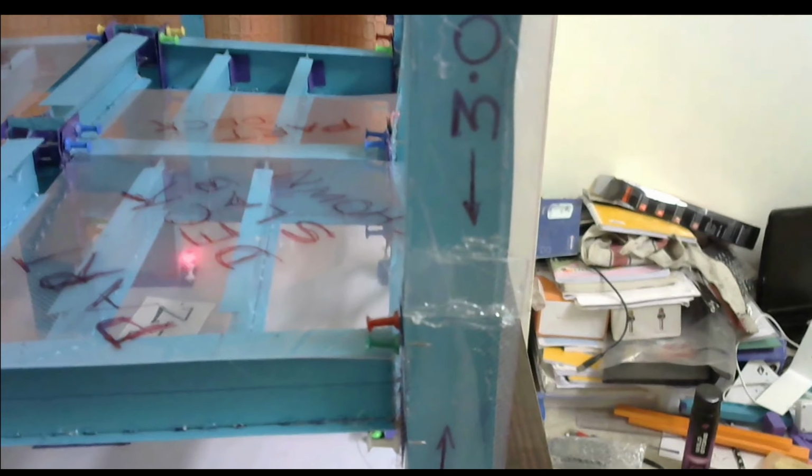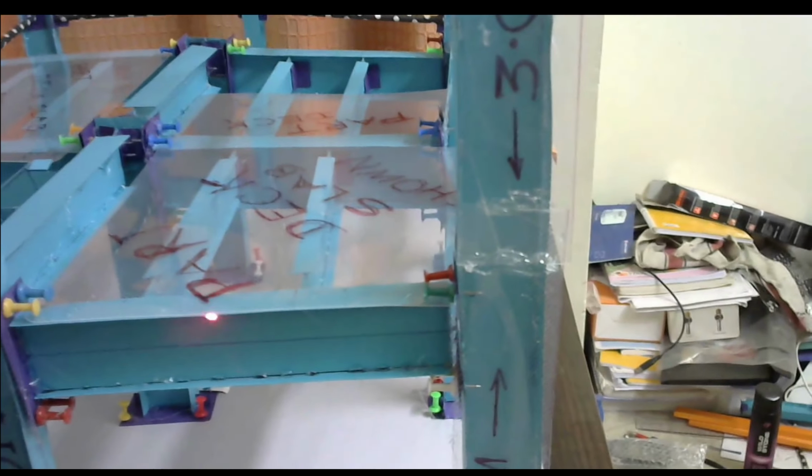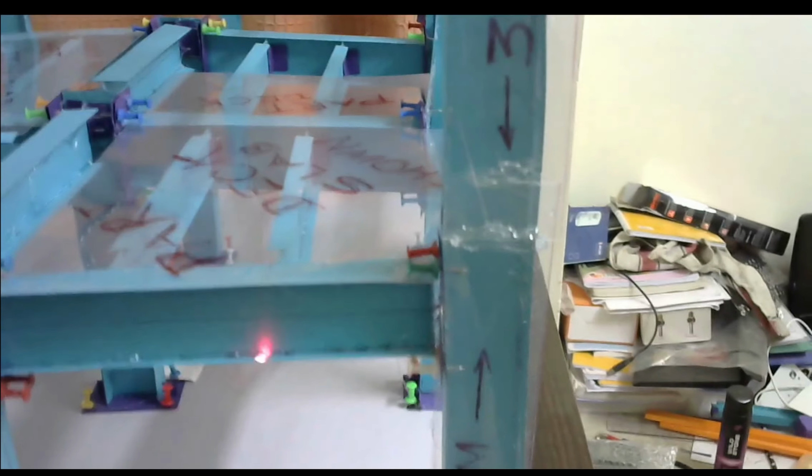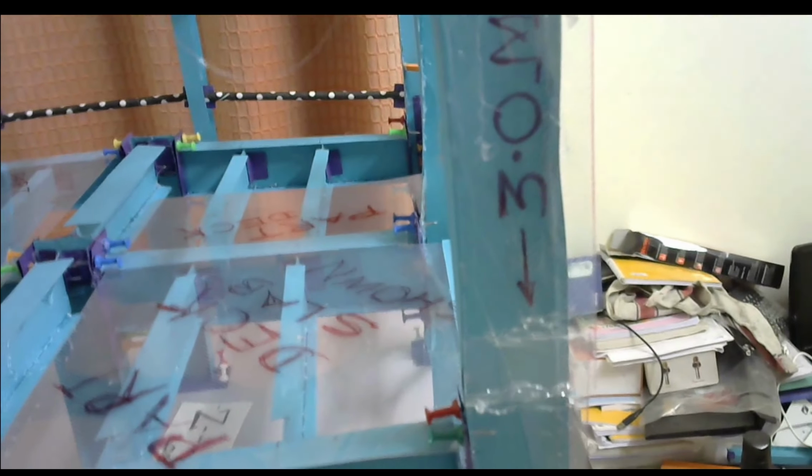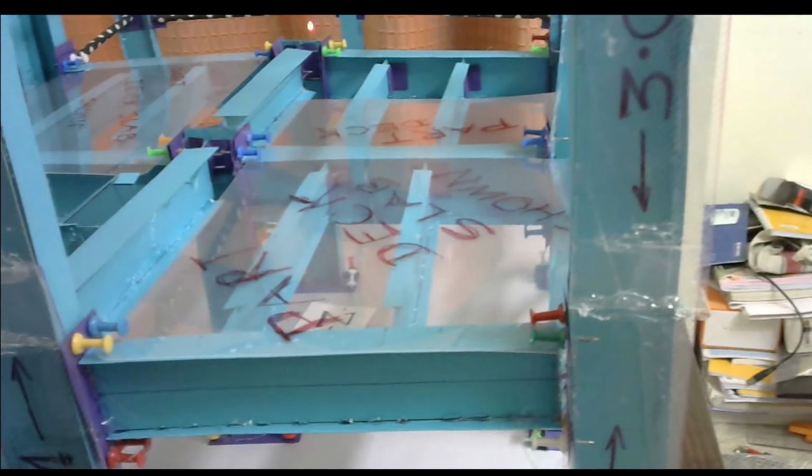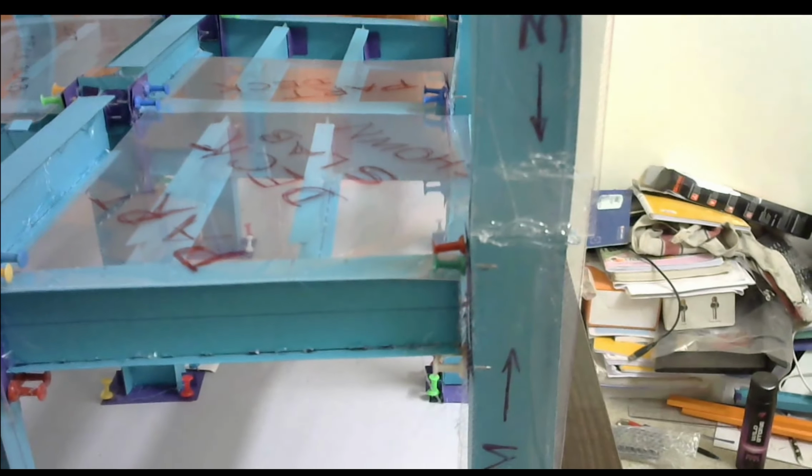There we have two joists here. So the joists are spaced at 2 meters. So LX and LY will be 2 meter, but LZ will be 6 meters. So for all the cases here, for this beam, LX, LY is 2 meter, LZ is 6 meter.